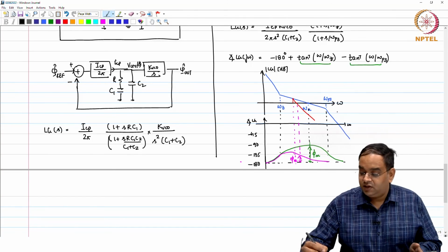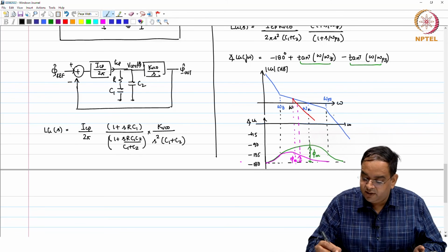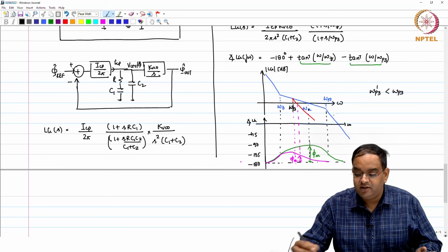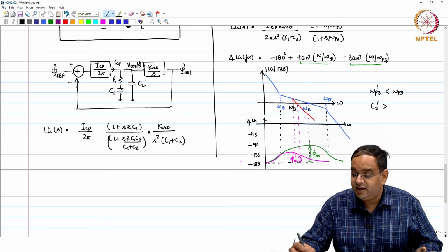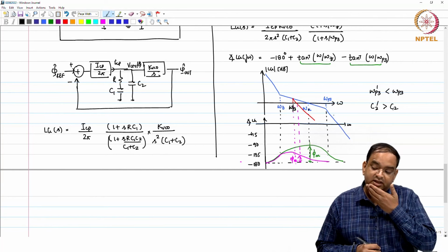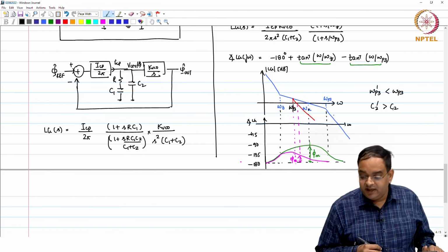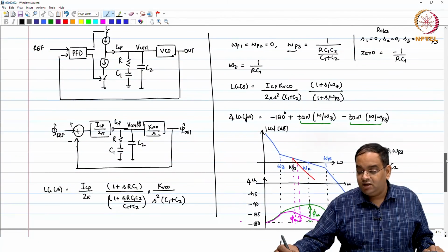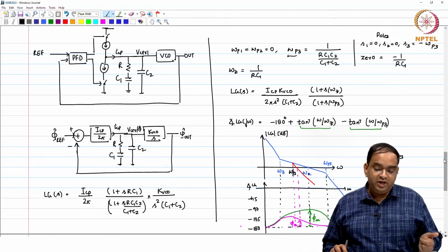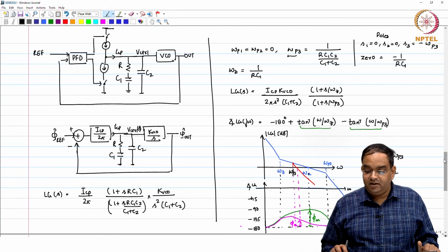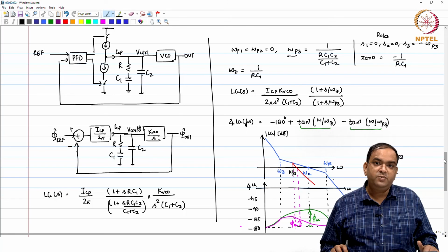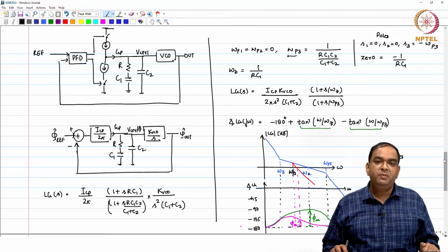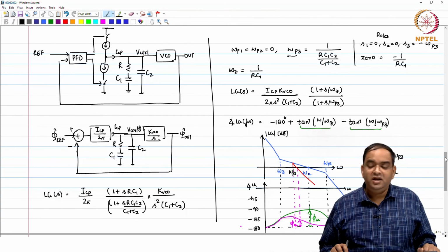Okay. So, I will write this as omega p3 dash. So, omega p3 dash is lesser than omega p3, and you can say C2 dash is greater than C2. C2 dash is the capacitor which you are using for omega p3 dash, and it appears that the phase margin is reduced, right. So, now as we introduced another pole in the system, what we found is that yes, you can reduce the control voltage ripple, but you make your PLL more susceptible to instability.